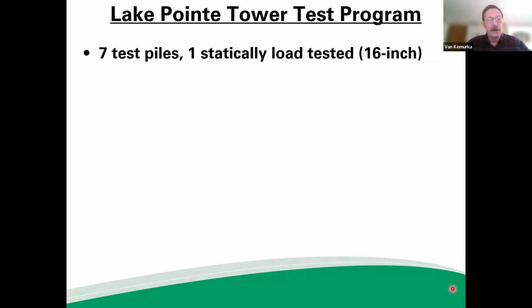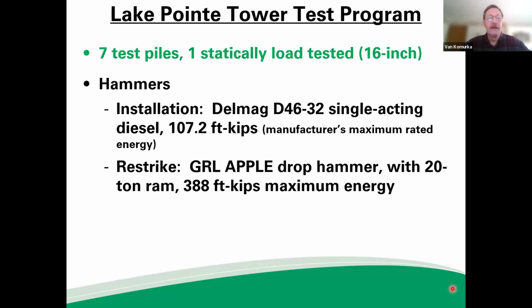7 test piles of those various diameters. 1 was statically load tested. That was a 16-inch. The hammer used to install was a Delmag D46, 172 foot-kips manufacturer's rated energy. On restrike, because the piles would have set up and would have to mobilize more resistance than that hammer was capable of, we mobilized a GRL Apple drop hammer configured with a 20-ton ram that had a drop height and ram combination that gave it a potential to mobilize 388 foot-kips